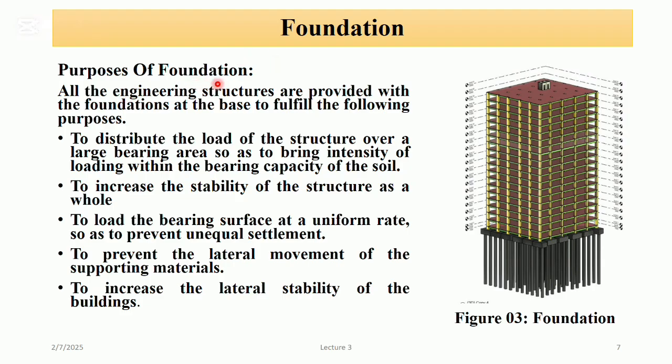Purpose of foundation. In all engineering structures, we provide foundation at the base level to get the following properties: to distribute the load of the structure over a large area. The second one is to increase the stability of the structure and its lateral stability, and to prevent unequal settlement, and to prevent the lateral movement of the supporting material. So these are the purposes of foundation.